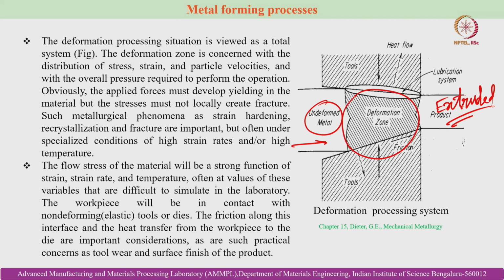It is concerned with the distribution of stress, strain, and particle velocities, and with the overall pressure required to perform the operation. Obviously, the applied forces must develop yielding in the material, but the stresses must not create local fracture or crack propagation, which can damage the surface and also subsurface features of the workpiece undergoing deformation processing, and in general it can lead to catastrophic failure or the generation of subsurface cracks, which can cause catastrophic failure when the deformed object is subjected to in-service loading conditions.